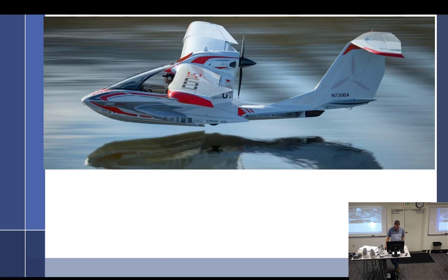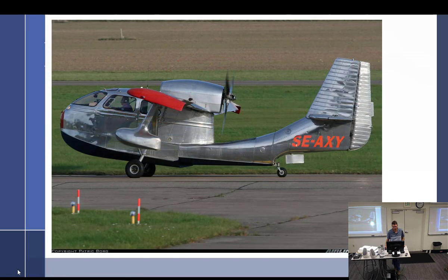More susceptible to damage from rocks kicked up by the landing gear or by spray. So they're almost always, for a lot of reasons, mounted much higher. I suppose if you mounted this one much lower, the prop would cut this in half right there. So that's another reason why you have to mount them high, is because you have airplane parts down below. But yeah, again, same thing. Rocks will be kicked up from here, getting the prop.